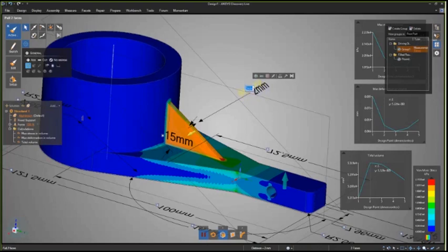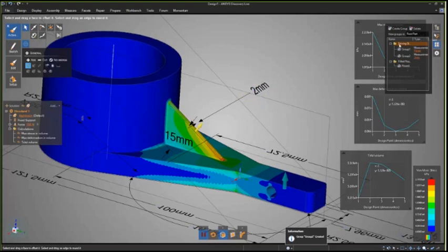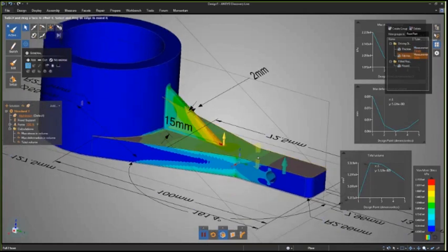So that P is having trouble showing just because it's on top of that. So here I'm just going to use this create group button. So this was thickness of the rib. And then this was, switch this up to rib height. And let's also set one up for the height here.